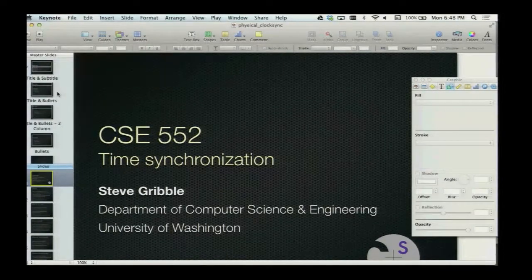Temperature, it turns out for these things, does affect the rate at which it will mechanically vibrate. Luckily, it's not a linear effect, it's a sublinear effect, which is why people choose that material. Yeah, well, and when they design the circuits, if you care about that, they'll actually put them in little heaters. Oh, really?